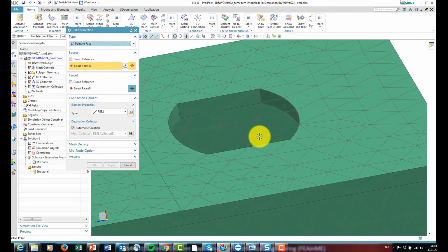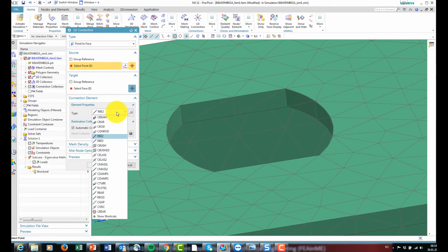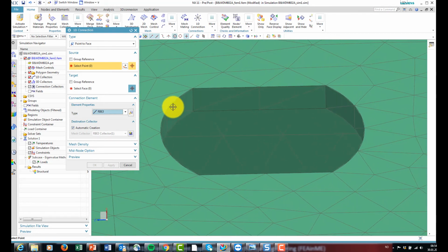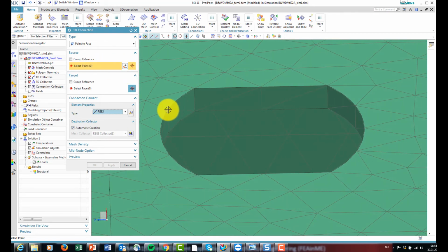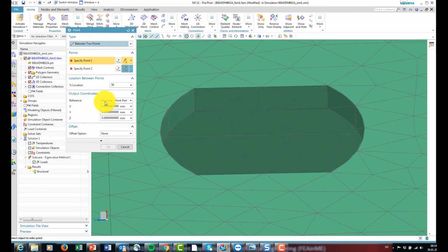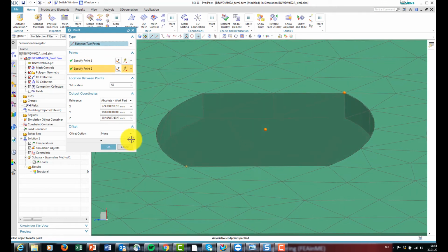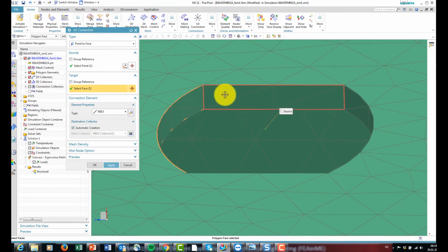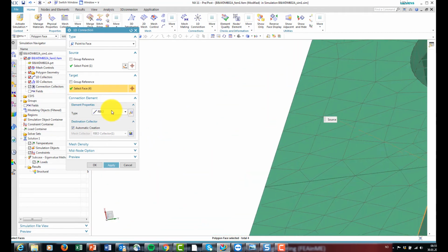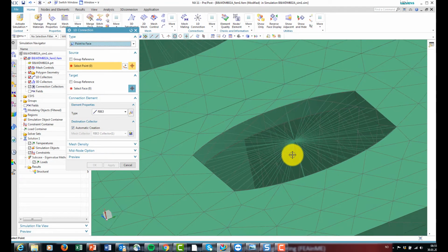And then I have my tweeter, and I use the same technique, but here I think I'll use RB3 again. Then we can see how the different techniques work. To select a point, I don't have a center point here, so I choose the dialog here, and I select between 2 points. And I select 2 diagonal points here. Then I will have the center point. And then I can select the surrounding faces. And here I choose to use RB2 because I imagine that the tweeter is not very stiff.